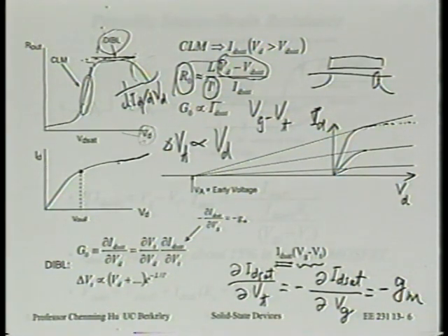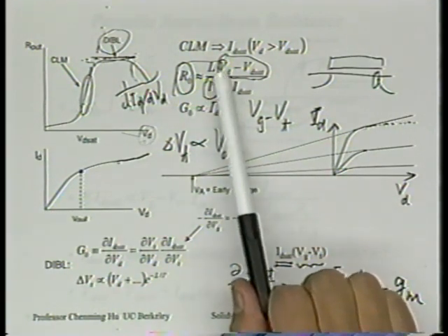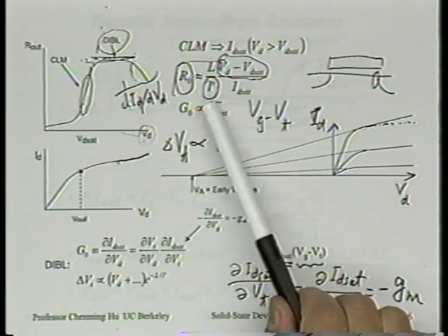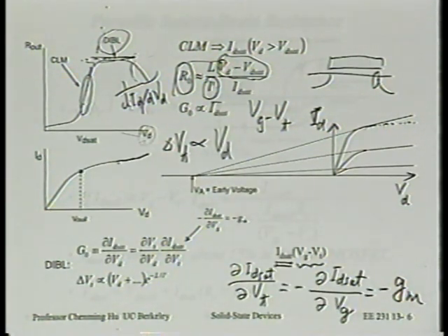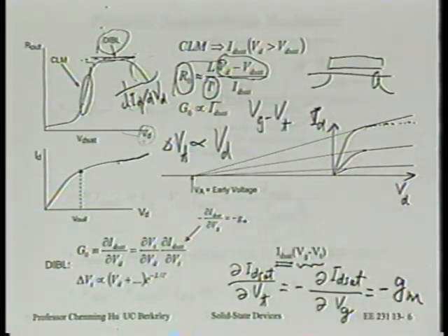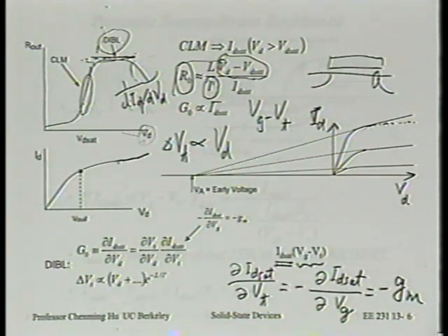And output resistance in some ways is the finale of this lecture, and turns out to be proportional to the channel length, proportional to Vg minus Vt, inversely proportional to square root of Tox and Xj, and inversely proportional to ID set. Now this reminds me, I haven't talked about this term yet, so let's talk about this term in R out. The ID set dependence.